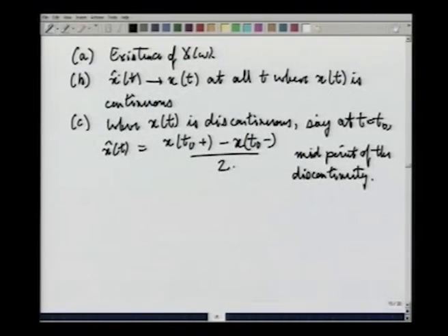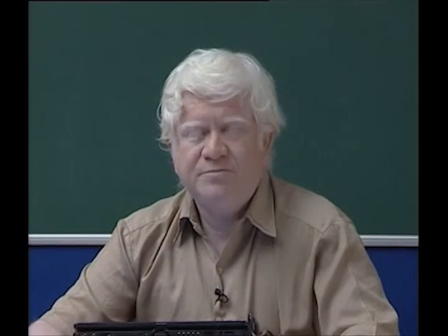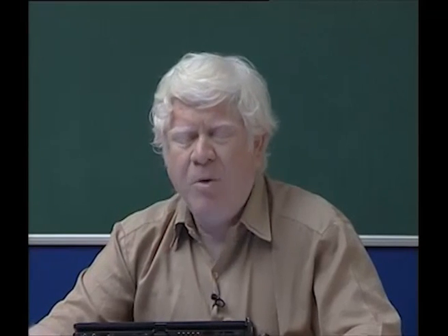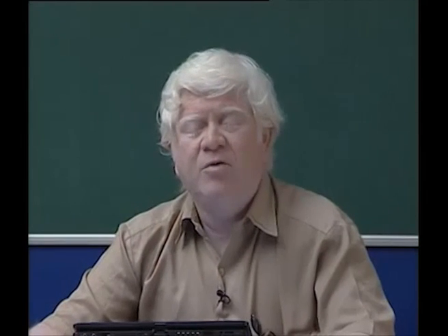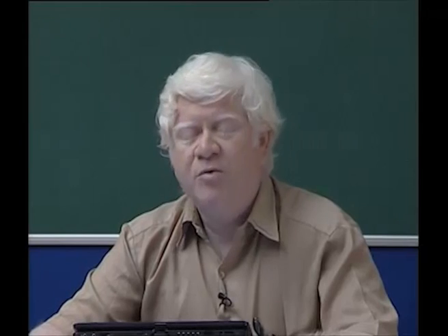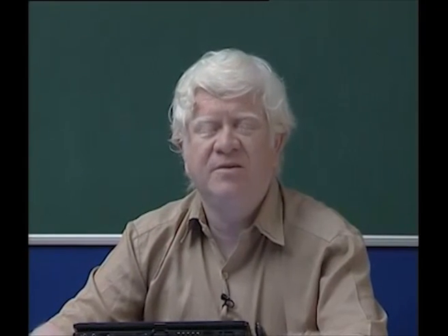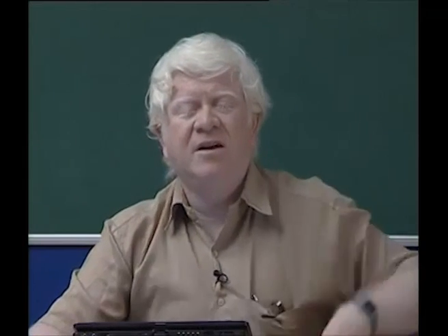With this, we now have an idea of what to expect from the reconstructions and representations that are provided by the Fourier transform. Now, one important constraint on the Fourier transform you see is that the Fourier transform will exist only for signals which are finite energy. Signals should have finite energy, otherwise the Fourier transform will not exist.